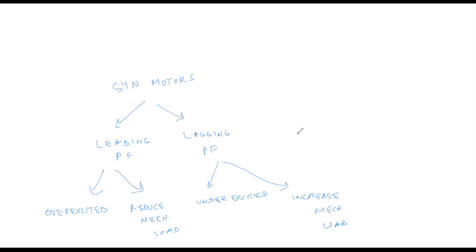The recording has already been made available on the LMS, and in these two methods, I've also told you how it impacts the phasor diagram. For example, if you do not change the excitation of the machine, EA stays constant, because EA is a function of K into phi into omega, where phi is the main field on the rotor, and omega is the rotational speed of the rotor.